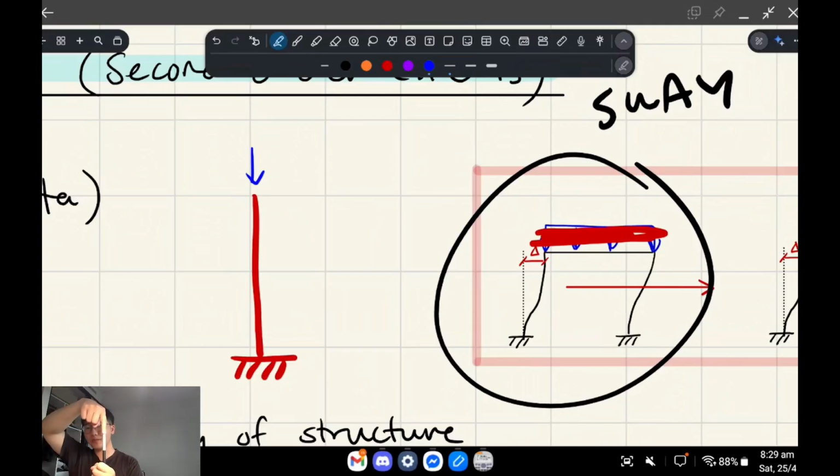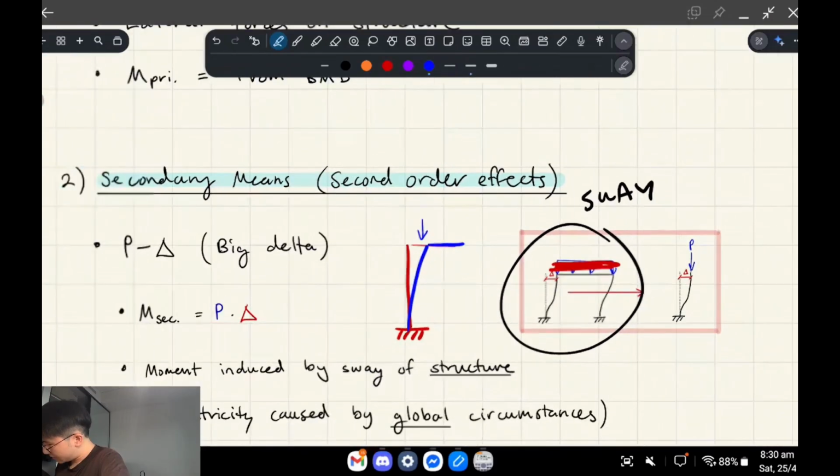But in reality, you have to account for something called eccentric loading, and that's if my finger, the point load, is applied off to the side, okay? And if it's applied here, it's basically going to cause this to bend over to the side. So, drawing that, pretend that this is connected to the beam and stuff like that. Basically, this would want to tip over like that, okay? For a sway frame, it would look like that.